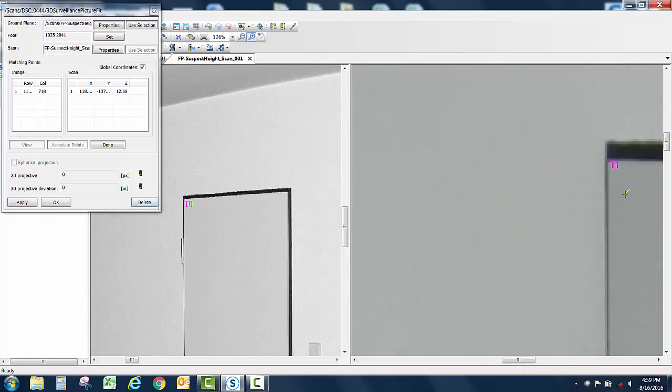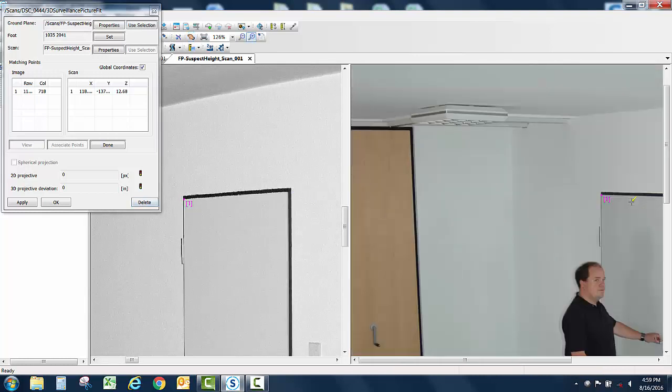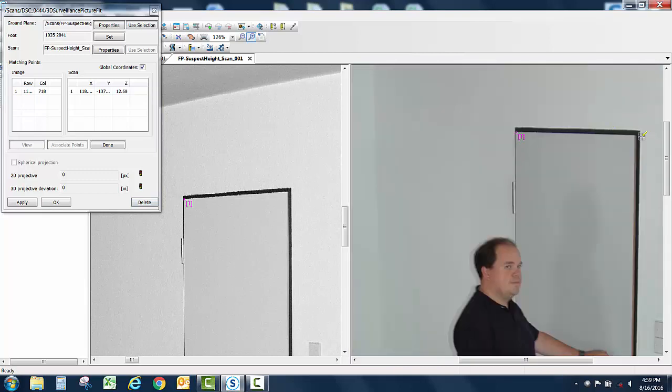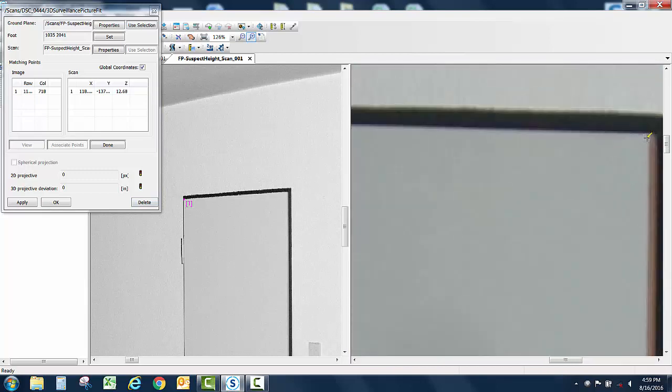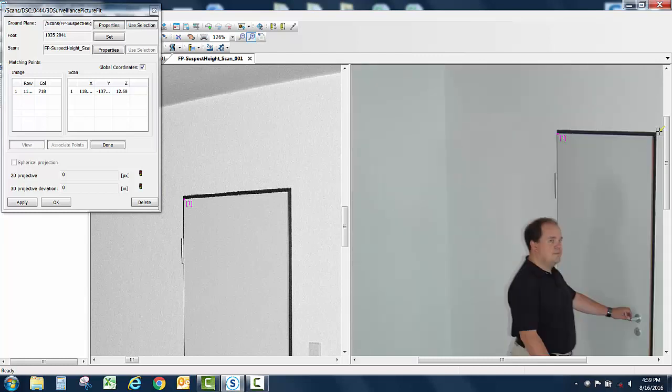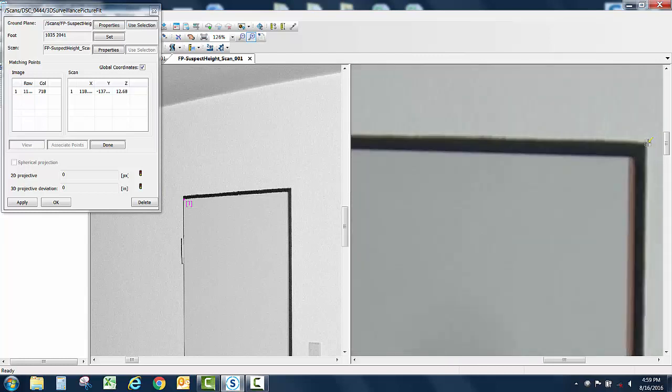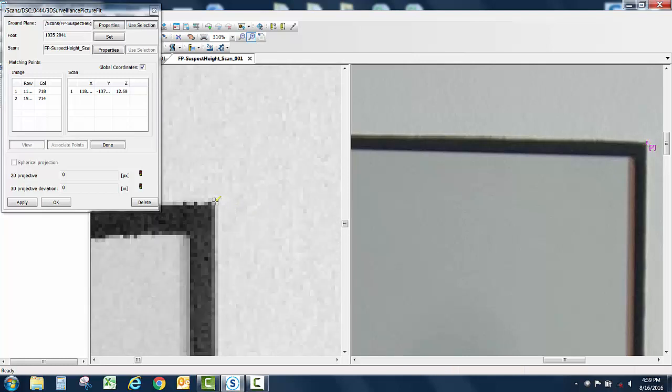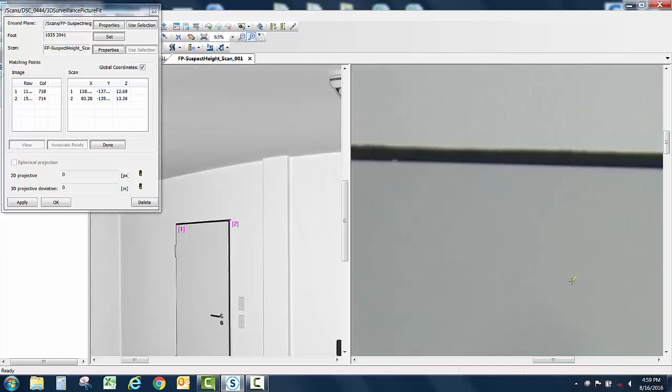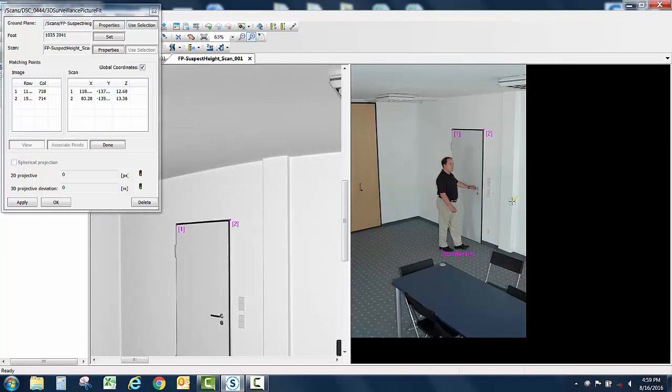So now you notice here while I was trying to move around, you have to use your pan and zoom using the control key on your keyboard to be able to move around. Just using your mouse wheel allows you to zoom out, and then when you identify the area you want to mark, just zoom in on that using your mark that you see on the screen along with your mouse wheel, and it'll just zoom on that area. Be very careful and really zoom in on these, because the further off you are, the greater your rate of error is going to be.